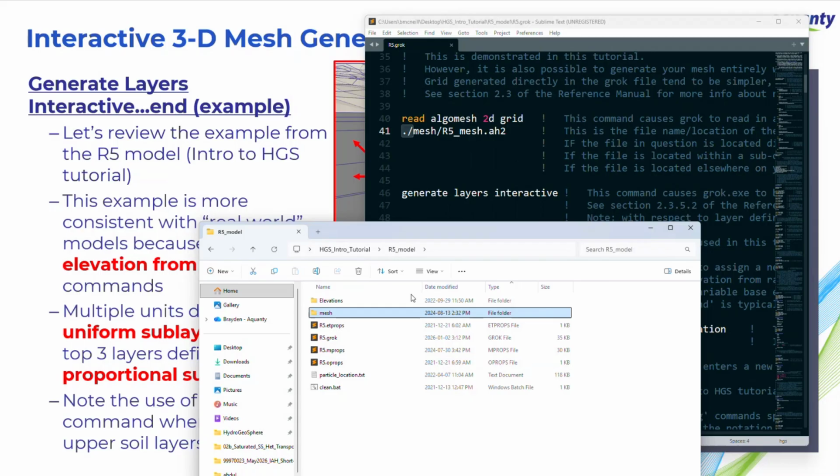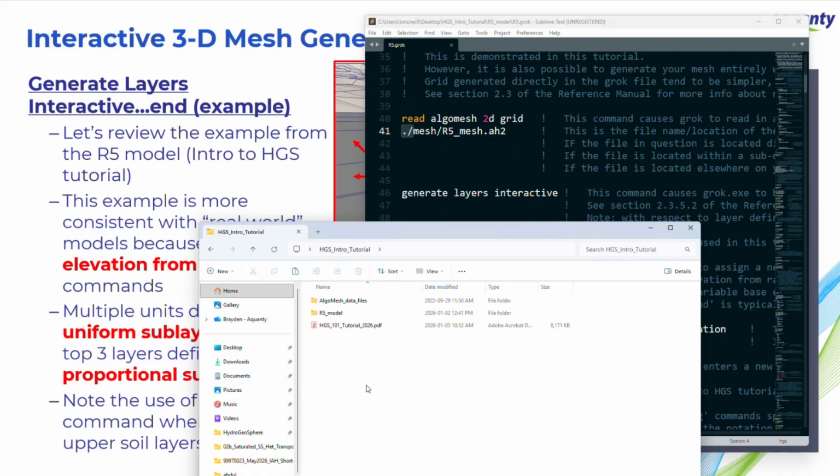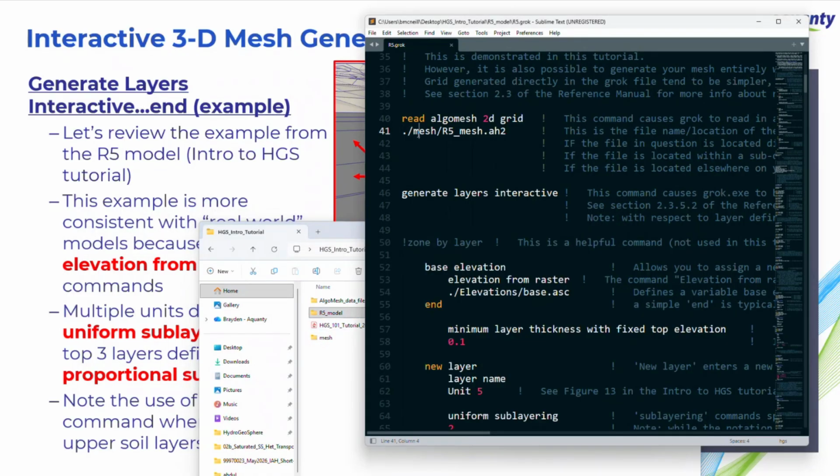If you have potentially a series of data files describing the model mesh, but you're going to end up building many, many iterations of the model, you don't want to necessarily duplicate the data within this folder over and over again. What you can also do is save some data outside of the actual project folder, and the relative file path then would just be ../mesh.